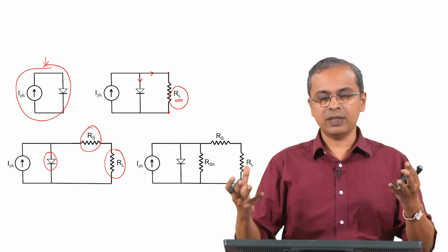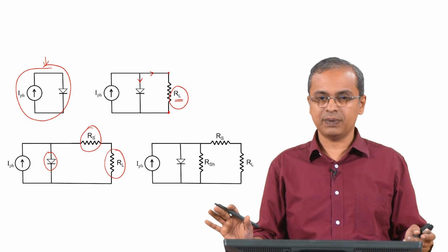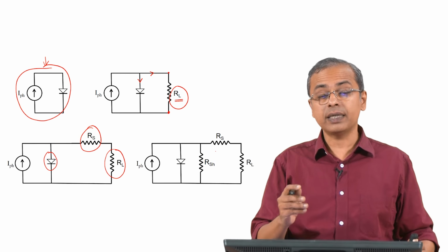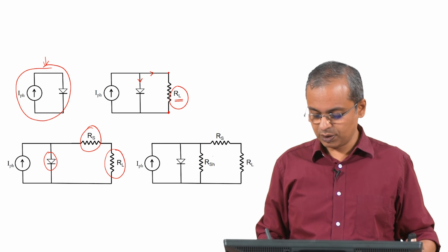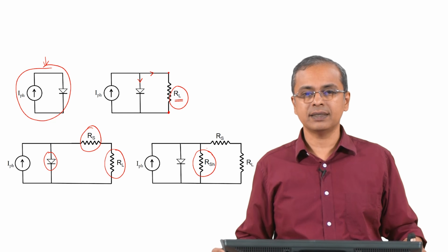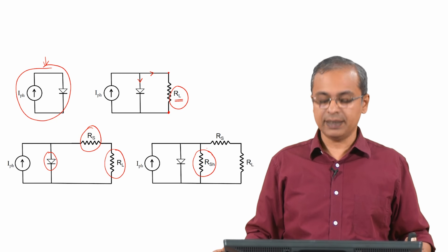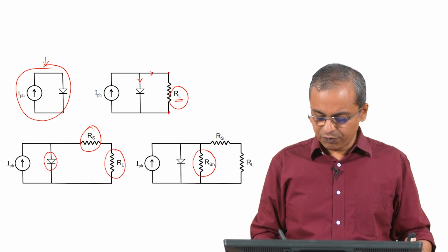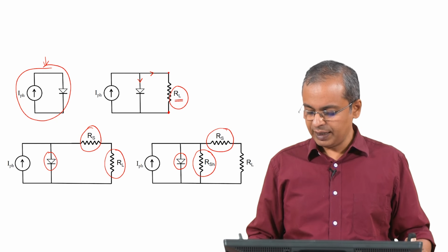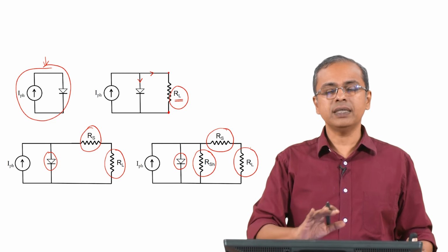So, the solar energy created all this, it created the possibility that you could have all this current, but some of the current basically got lost within itself, right. So, that photocurrent, some of it got lost internally because of the internal short circuit or internal recombination, so to speak, and so that is what this is. Okay, so, this is like a shunt resistor. So, it adds to the internal aspect of recombination that is going on. So, this is from the forward bias, this is from the recombination, this is the series resistance that you have, and this is the load resistor. Okay. And so, this is how the circuit looks.